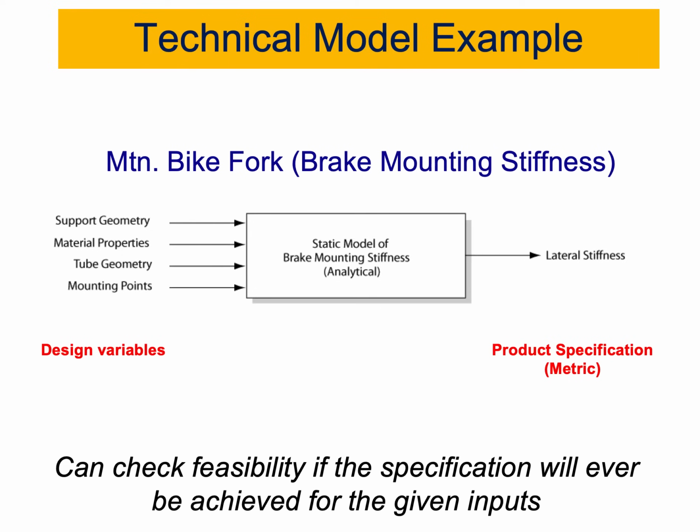Let's say if we are talking about strength, the elastic modulus, which is a material property. So let's say I will use this model and I will put the elastic modulus to be 10 gigapascal. And then I will repeat it again with 5 gigapascal and then 25 gigapascal. And I will see what the output will look like.